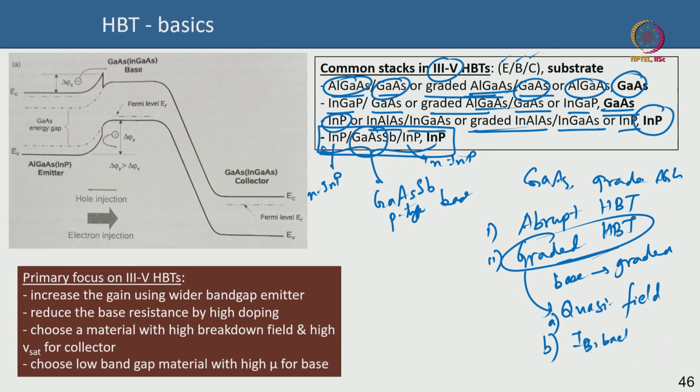Your layers should have lattice mismatch to an acceptable degree such that the layers do not relax and create misfit dislocation. Ideally you want them to be lattice matched, and you have a lot of material options to choose from, because you can go ternary, quaternary alloy, and play with the band gap, the electron affinity, the band gap tuning, the band alignment, etc. to a large extent. Okay.